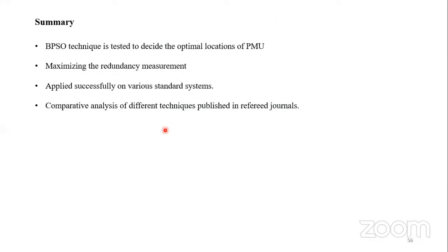Now, what is the summary of this topic? We have used the binary particle swarm optimization technique to solve the optimal PMU placement problem. Our main objective is to maximize the measurement redundancy, and we are also planning to successfully implement this BPSO technique on larger-size networks.